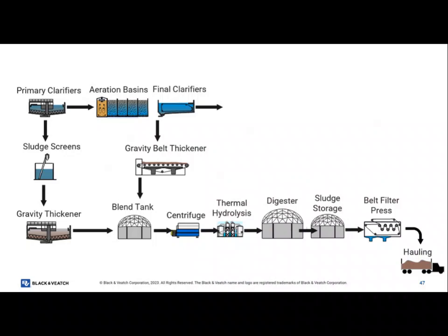In between the sessions, for that VFA that was coming back around, we showed that increasing your mixed liquor concentration basically made the aeration basins become storage. And what kind of happened in the break is we were discussing what actually happened on the liquid side of all these solids capacity issues. Besides building up mixed liquors, what happened here?